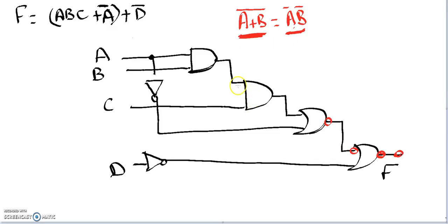We have an AND gate and we have two inputs, so they need to be negated. By adding these two bubbles, this gate became a NOR gate. However, since we added a bubble, we need to cancel it out. So we have to cancel it at the other end. So this is a bubble-to-bubble connection. The same applies here. How about this one? The same applies to this end.